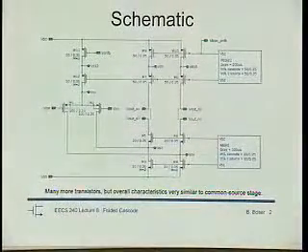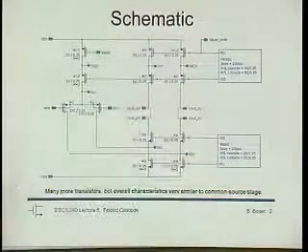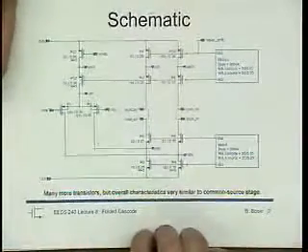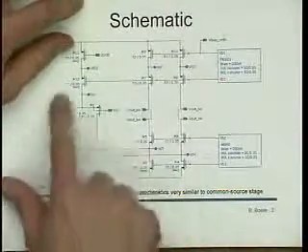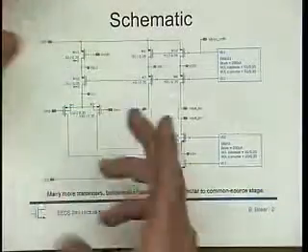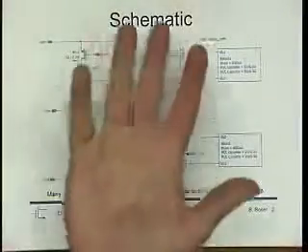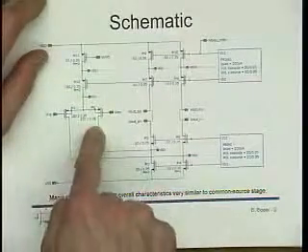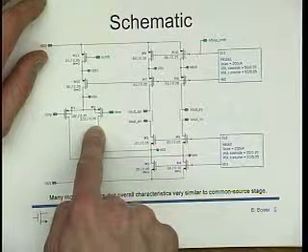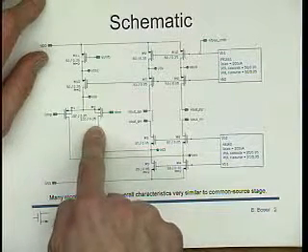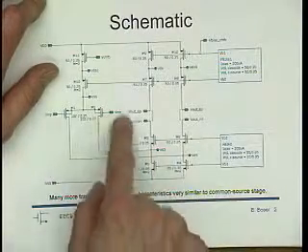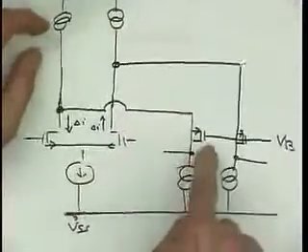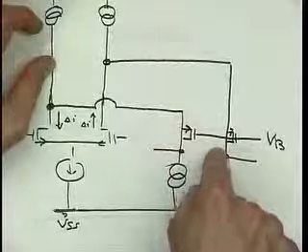Okay, so now next interesting question: should we have NMOS or PMOS inputs? One argument, first of all, is whether we want to tie the bulk to the source, and then we may be constrained. Like in our process, we can use only PMOS devices. The other thing is, if we do this, then we have relatively fast transistors here at the input. That gives us a large unity gain bandwidth. But if these were NMOSes, we have fast transistors here, high unity gain bandwidth, and then we have the PMOS cascodes.